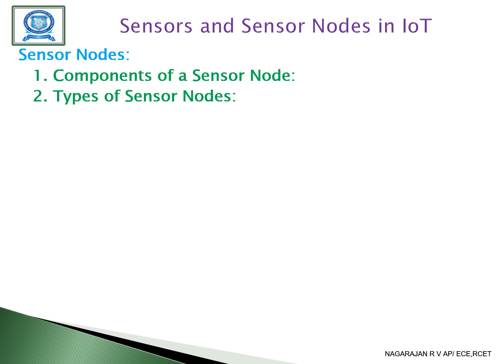Then the microcontroller, a compact integrated circuit that processes data from the sensor and controls communication and power management. Then the communication module enables the sensor node to transmit data to a gateway. Common modules include Wi-Fi, Zigbee, Bluetooth, and LoRa. And the power source provides energy to the sensor node, typically batteries or energy harvesting systems.